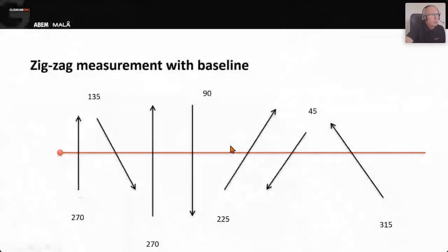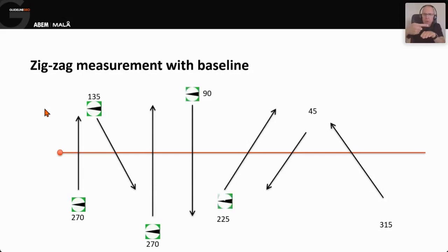So some other ways of measurement then, like I said earlier, we can do some different angles. You don't have to go at right angles along the baseline. What I tend to do there is if I come across at a slight angle, I will drop the monitor on the GPR down flat, and I'll move the compass around. You'll see it on the top until it points back to the beginning of the baseline. So you can actually put different angles in there.